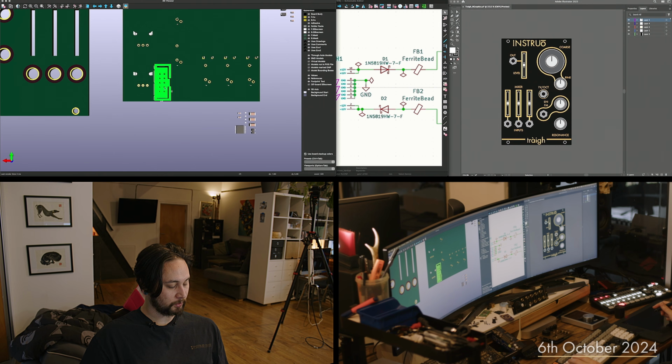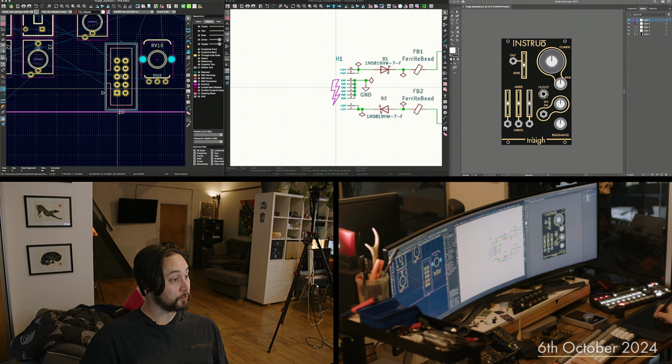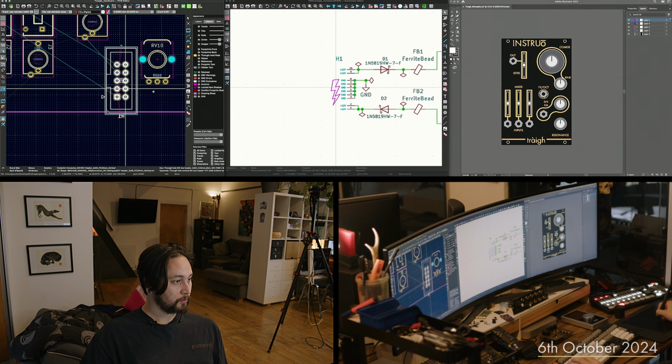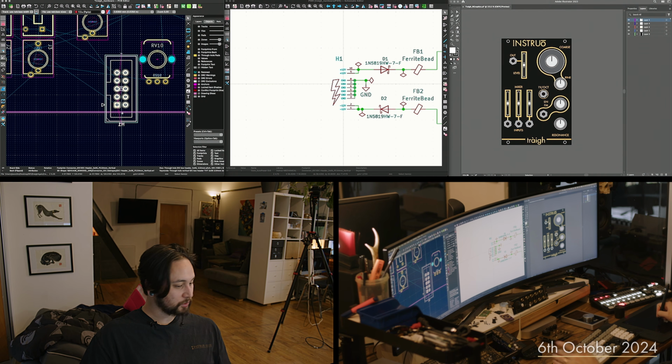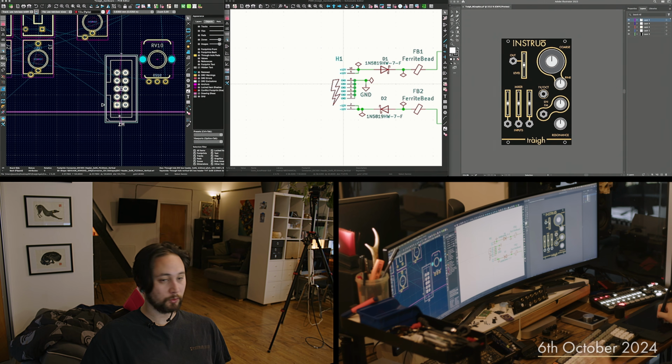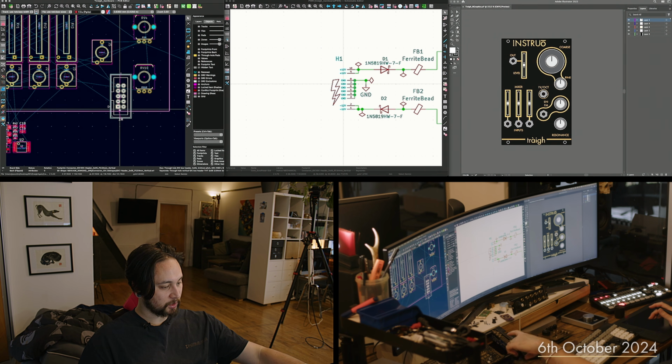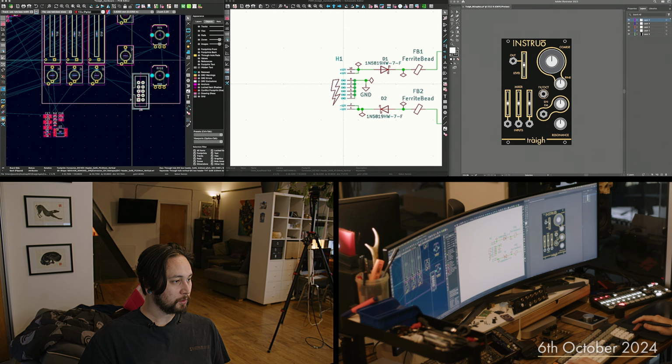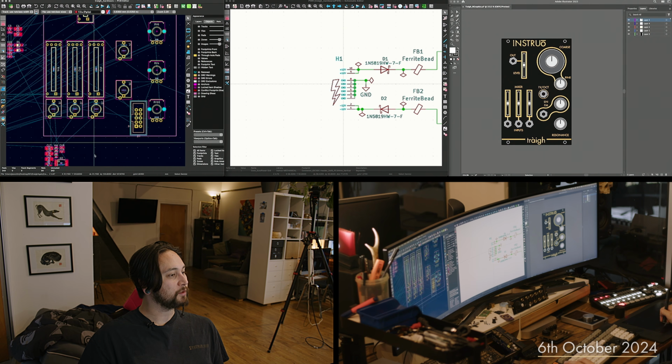If I was doing non-shrouded headers, then I might be tempted to move it down there. But the bottom of the actual power ribbon itself would potentially extend below, so that's where space constraints might come into play and not move too close to the rail. So leaving it there, that should be plenty.